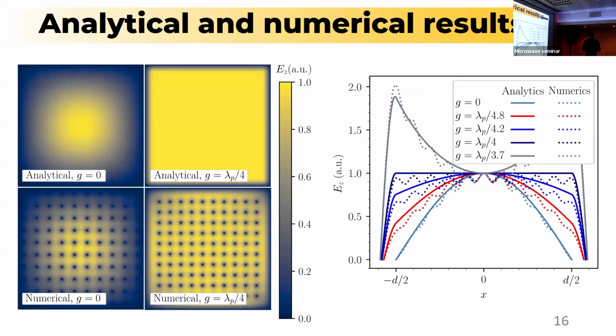In the resonators, you consider what happens to the ends of the wires. Are they soldered to a metallic wall? I mean the plane which is parallel to the slide. Yeah. Like in the conventional wire medium resonator from older works, there was an open end of the wires at the extremities, and therefore an open boundary condition was applied, and the mode could also be uniform along the wires.